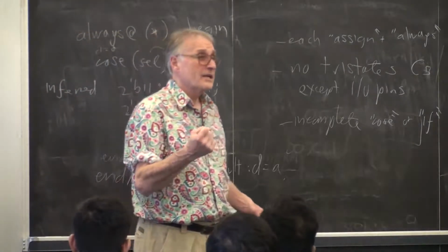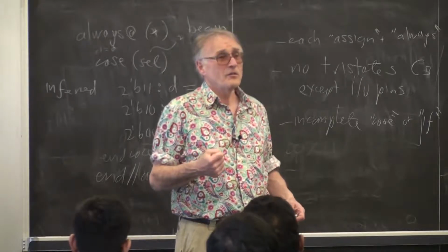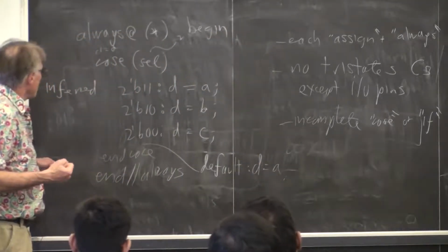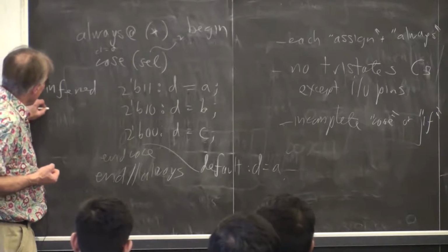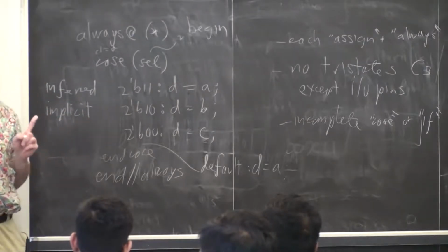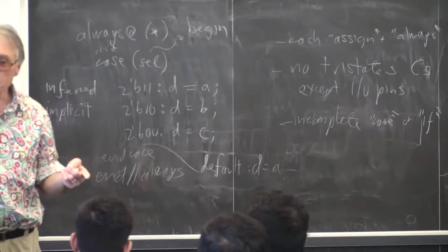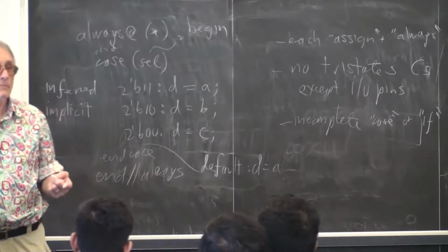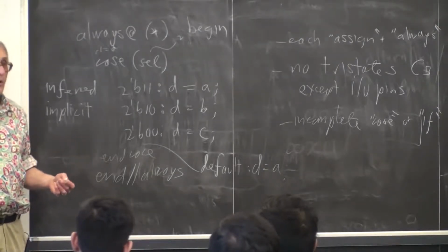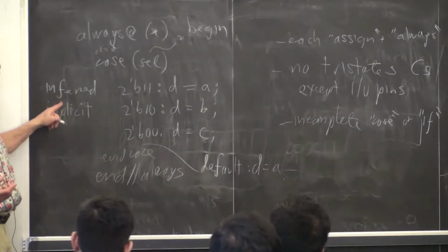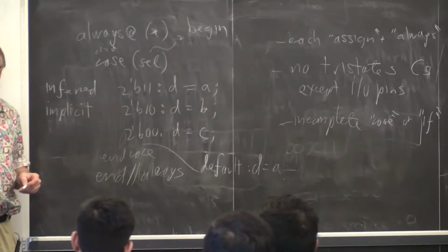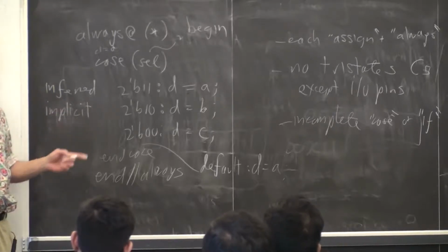Neglecting to declare is not an error. It is a warning, because if you just use a variable, it defaults to a 1-bit wire. And so you want to always search for the keyword implicit, because that'll pick up signals that you forgot to declare. If what you wanted was a 1-bit wire, it may work anyway. But if it's a multi-bit wire, it won't. So those are always worth searching for in the warnings. Anybody else have any keywords they like to look for? Those are the two that'll kill you.